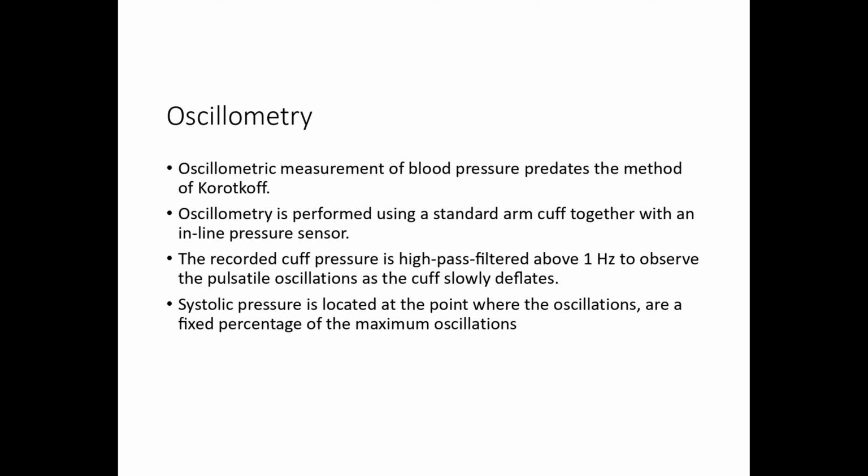The recorded cuff pressure is high pass filtered above 1 Hz to observe the pulsatile oscillation as the cuff slowly deflates,